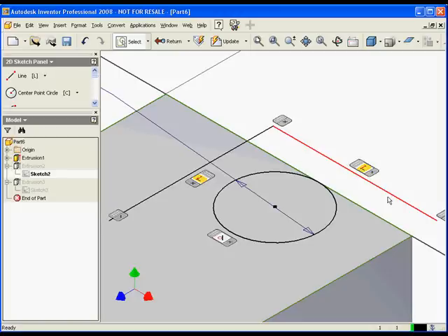As I executed the move feature option and brought it close to the edge of the face that I moved it to, constraint geometry was automatically placed inside of the sketch. Now in order for that constraint geometry to be valid, two reference geometry lines had to be projected from the edges of the block. What we see here are the remnants of that edit that I made.